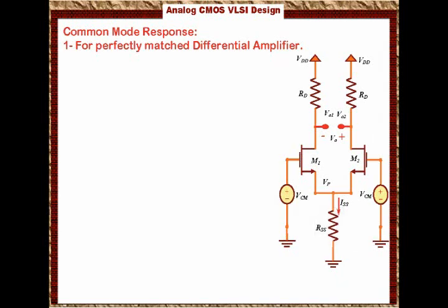So over here we found the equivalent resistance of the transistor looking into the drain, or we have inserted a resistor at the source. By any means, there is an equivalent resistance at the source of M1 and M2. Then we can find one equivalent half circuit for this amplifier. How are we going to get the equivalent half circuit?